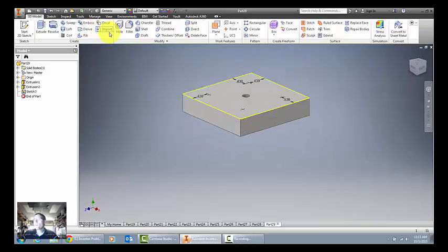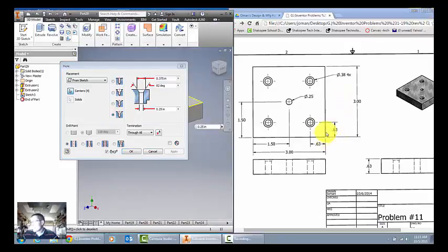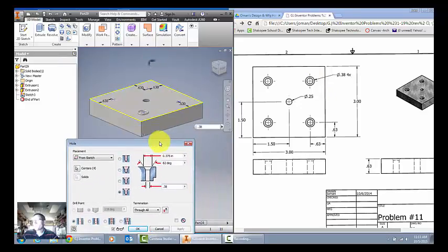Now we're actually going to use the real hole tool this time. There it is in 3D. Inventor knows to look for points when you're using the hole tool. If you bring your settings box out here, you can switch to the countersunk style right there. If I go back to our directions, we'll find that 0.38 is our hole size, so I need to change that right here. So the holes are a little larger.